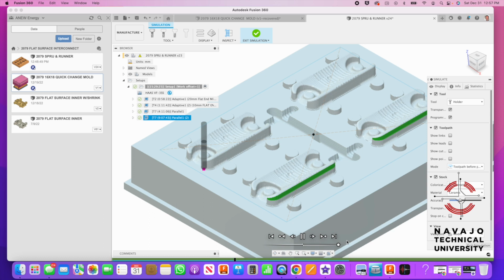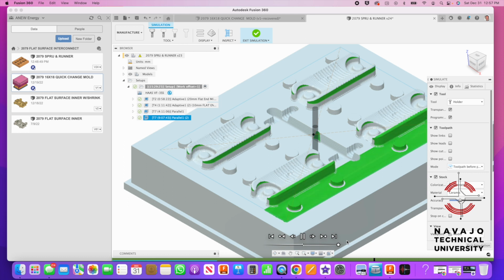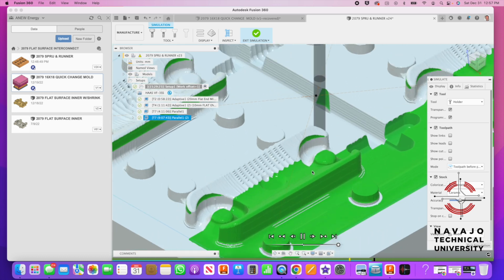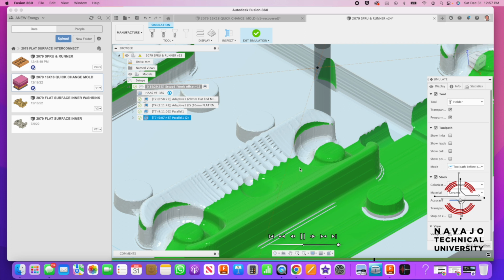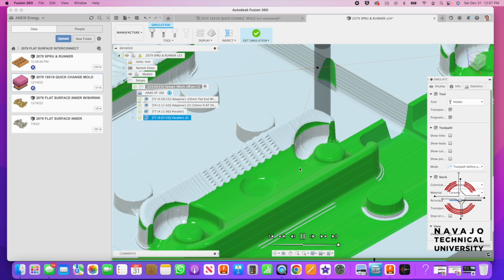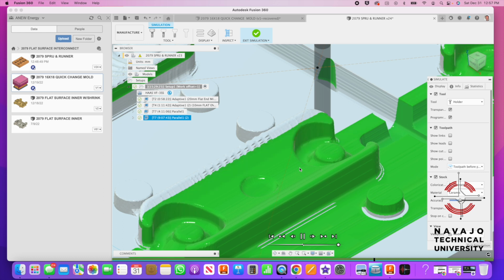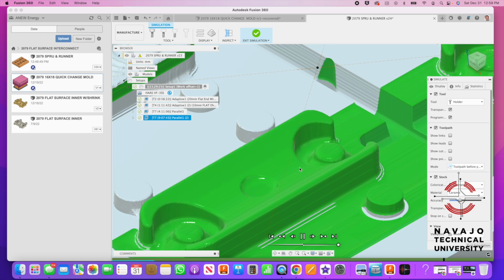So now it's starting to clean everything up, and we're going in there, and now it's going to go down and get closer to the surface, and it's really cleaning things up. It's just a 1 millimeter step over. So we get rid of all those scallops that we were seeing before. These scallops are starting to go away, and it's becoming a little bit smoother surface. We're still leaving a quarter of a millimeter, 0.25 mm, on the surface to do a final cleanup.